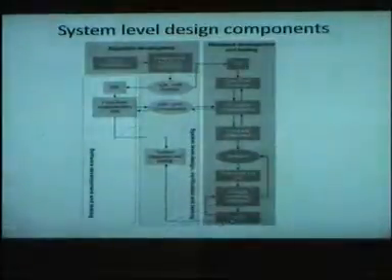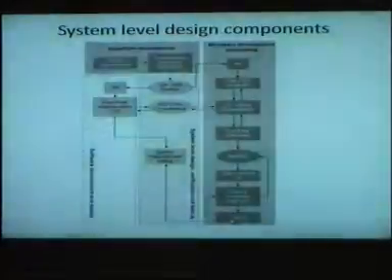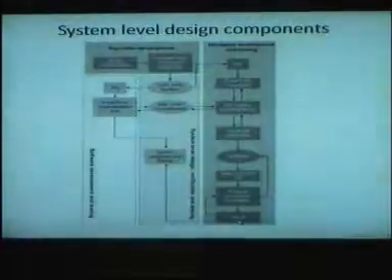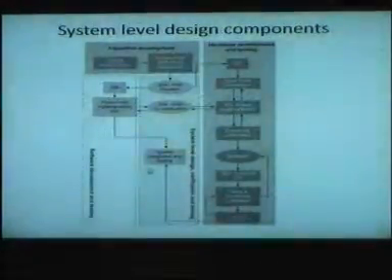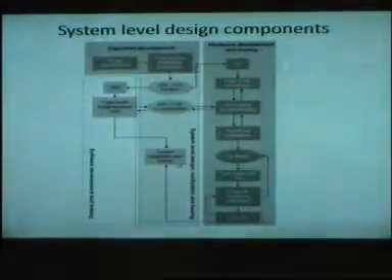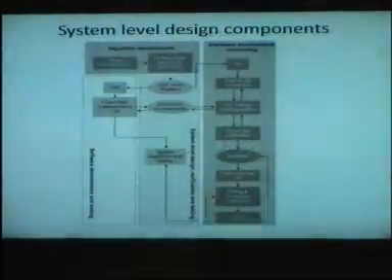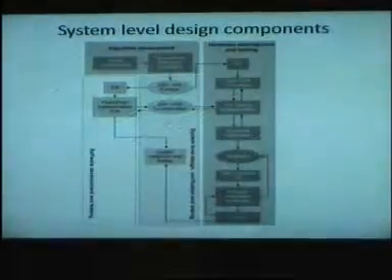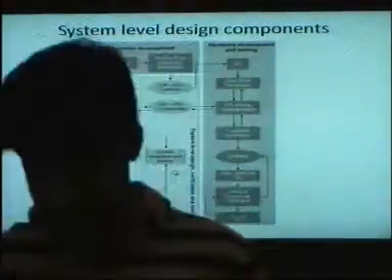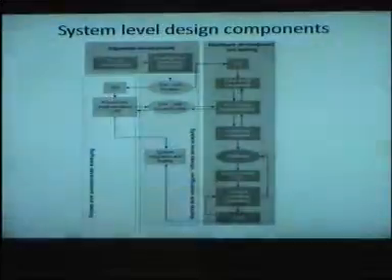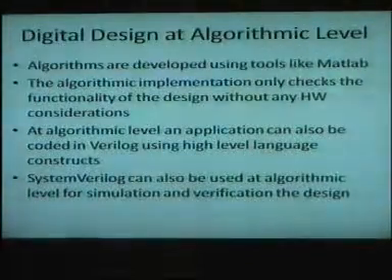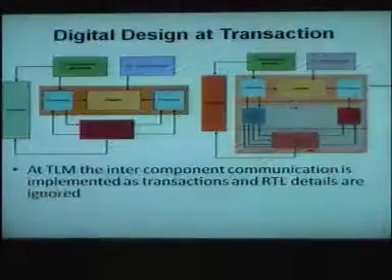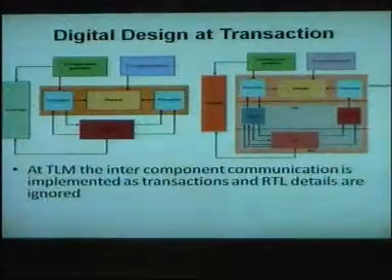And once you are happy, you download the bit files, or if you're designing an ASIC, you send it for layout, so you get the laid out chip, and then you do the system integration. But as a matter of fact, the integration and testing is happening in every stage of the design. So this is a system level design flow, and as I mentioned, I will spend time on this.